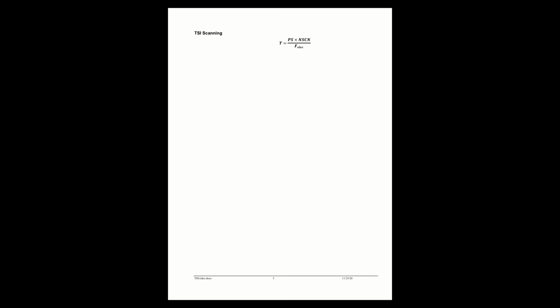Those two oscillators are going to go. After a certain number of cycles of the electrode oscillator, we're going to stop and capture that count, and that count is going to give us an idea whether the touchpad was touched or not. Now, the scanning happens periodically.